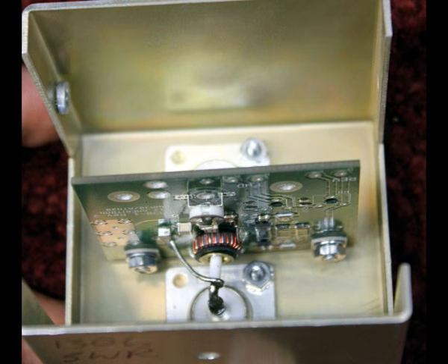If the null for the bridge set up by the trimmer capacitor isn't nulled for the particular impedance of the transmission line, then it's not measuring standing wave ratio at all. It's measuring the operating impedance error at that point in the line, between what the bridge is normalized for and what the operating impedance actually is at that point. The bridge has no idea what the standing waves are on the line.